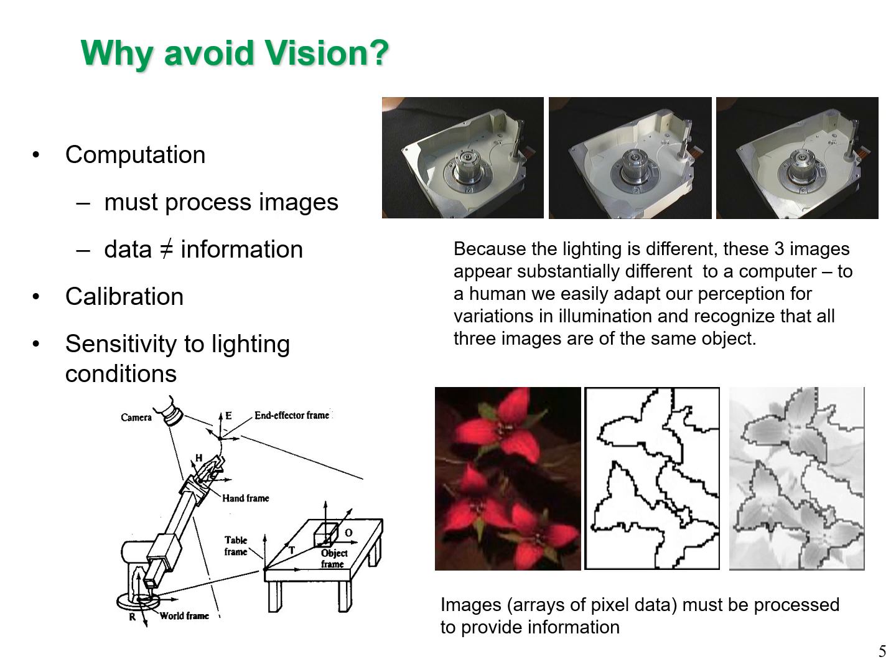Some of the reasons we try to avoid machine vision is that it cannot differentiate images as well as human beings. The above example shows the same components in three different lightings. A human being can easily recognize the different components as one, but machine vision takes time to recognize this because it is sensitive to lighting conditions, and it processes the image as pixel data.